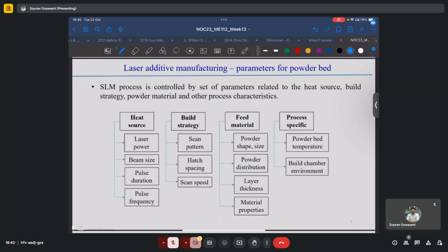Tensile residual stresses are generally experienced when large temperature gradients exist in a powder bed setup. And to decrease this temperature gradient, we can preheat the powder bed to say anywhere between 300 to 600 degrees. So that now when the powder is deposited with some superheat, say 1600, the temperature difference between the deposited material and the bed is only 1000 compared to what would have been nearly 1600 before. So this can lead to reduction of tensile residual stresses. As we know, tensile residual stresses are the ones mostly responsible for delamination, cracking, and other similar defects.